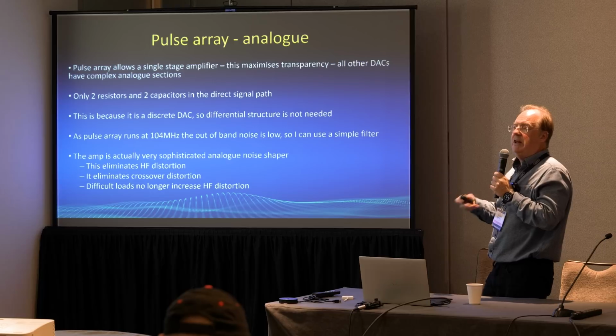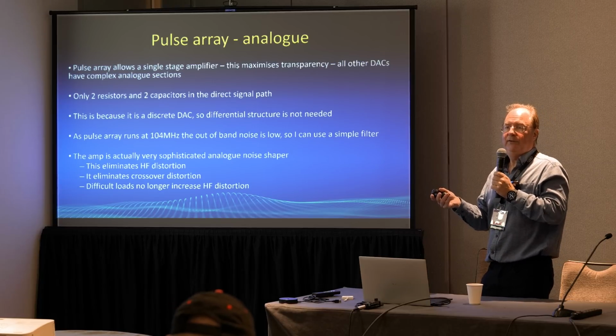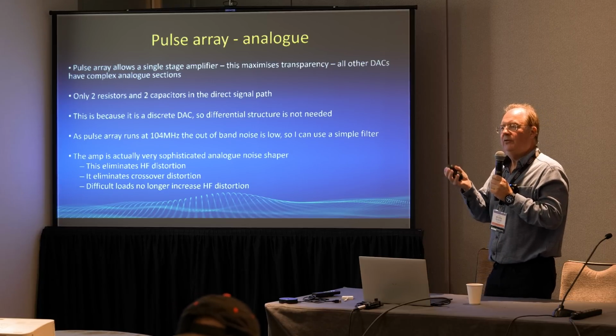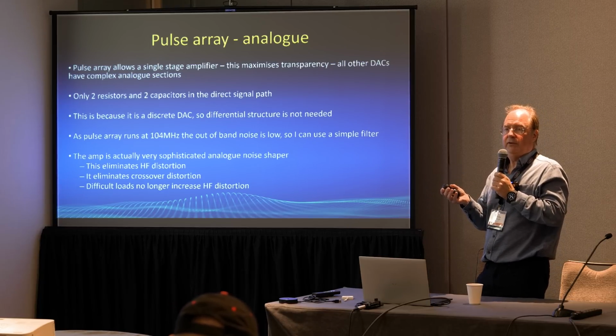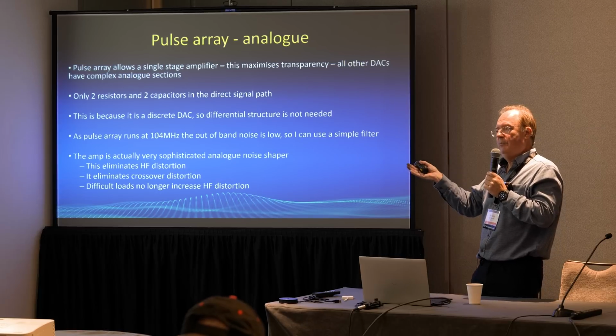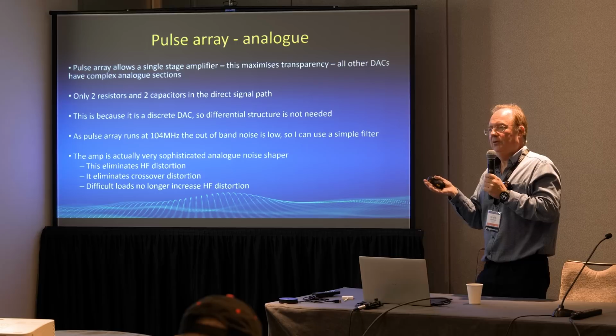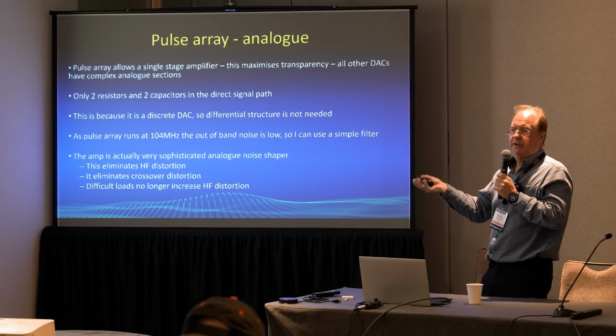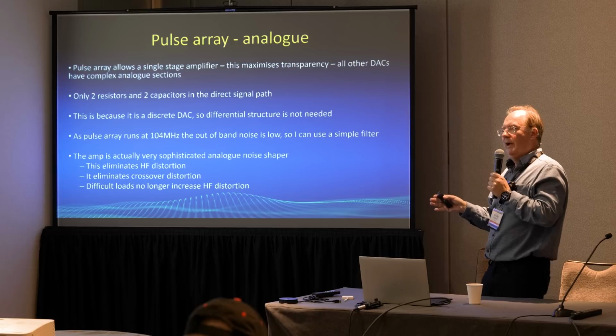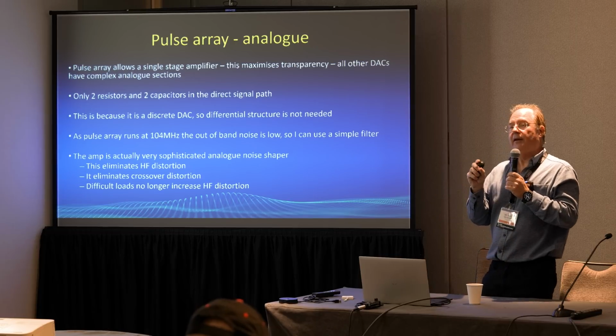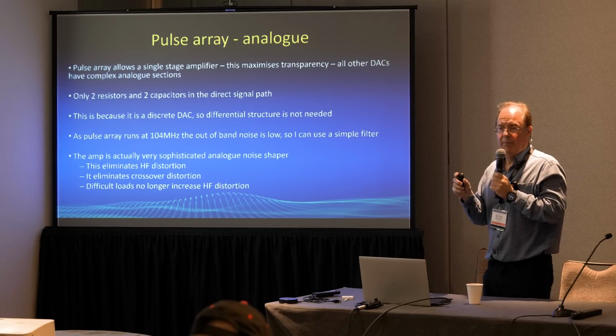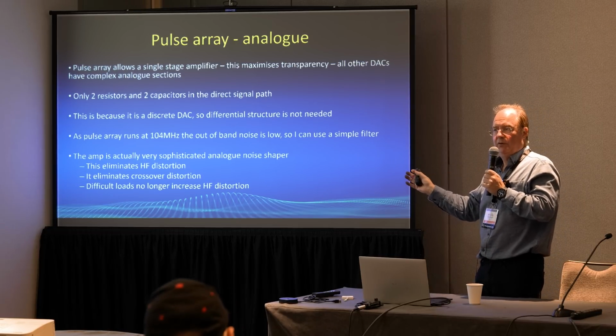And when you load it, like a TT2, for example, you see no change in distortion characteristics. So you can put a 300 ohm load onto a TT2 running at 9 volts, drop down to 8 ohms. The only thing that will change will be your second harmonic. The higher order harmonics will not change at all.